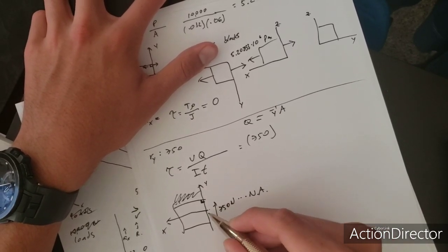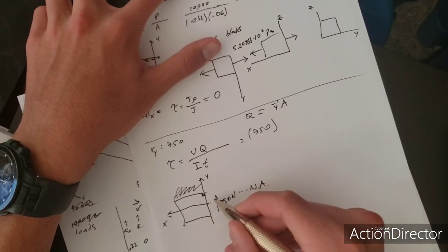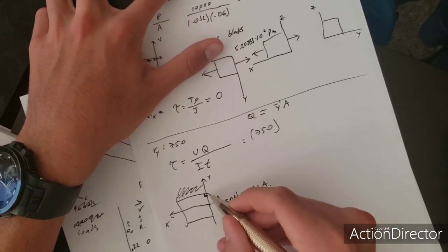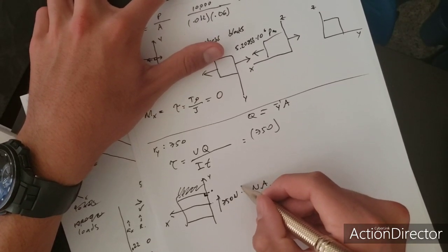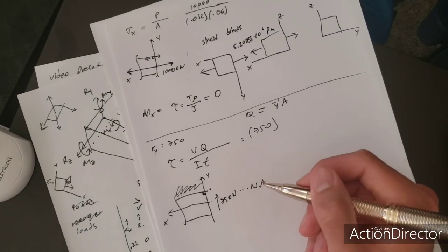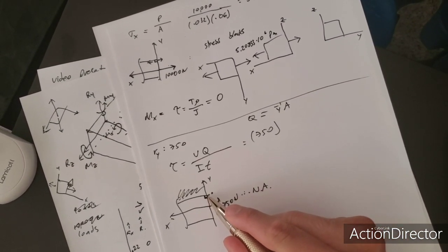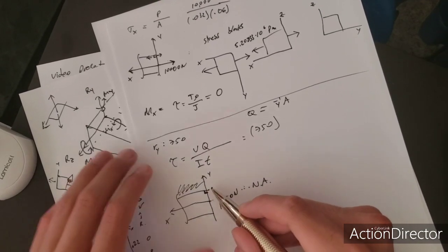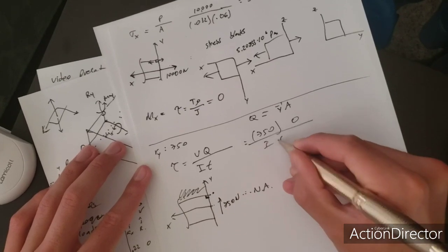And as you get out of the middle in either direction from the neutral axis, then it's going to get closer and closer to 0. Here should be 0. And here you have just a parabolic function that tells you how much your transverse shear is. So here should be maximum, here should be 0, because the Q, the area above, is just 0. So everything goes to 0.